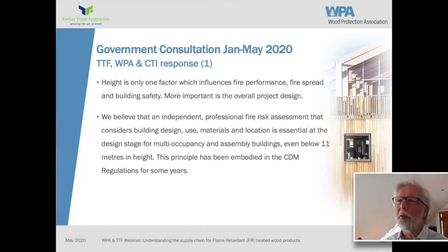And when you looked at a photograph of those buildings, which were less than 18 meters, I think anybody who understood the principles of fire protection would have said that timber should be flame retardant treated. But because the building was less than 18 meters, it wasn't, and the consequences were quite significant.